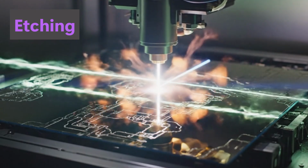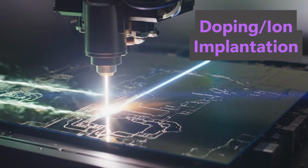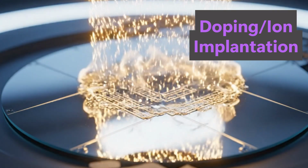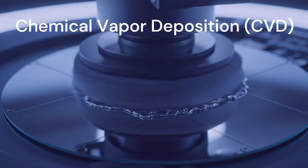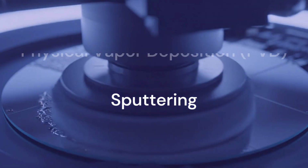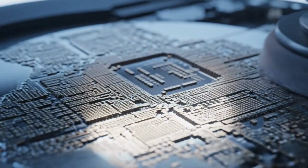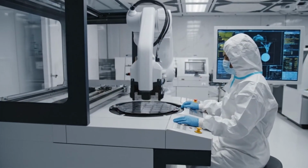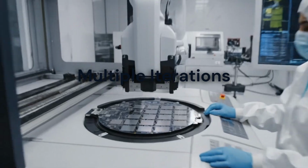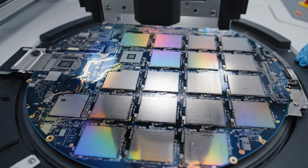Etching removes unwanted material, while doping or ion implantation introduces controlled impurities to form N-type and P-type regions. Thin films are deposited using techniques such as chemical vapor deposition, physical vapor deposition, sputtering, and evaporation. Multiple metal layers are added to form interconnections, and chemical mechanical polishing ensures a flat surface after each layer. These steps are repeated many times, gradually building up billions of transistors and interconnects on a single chip.